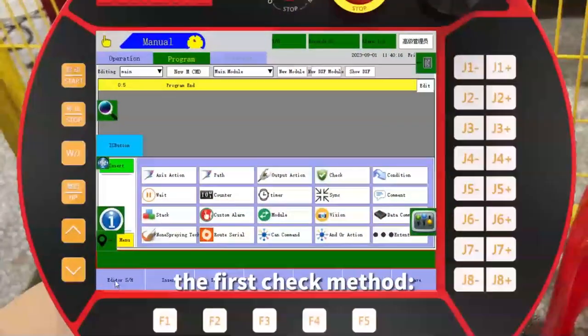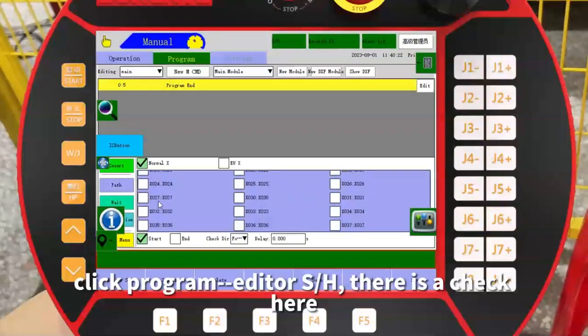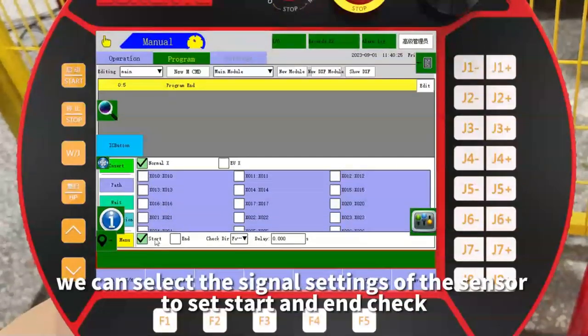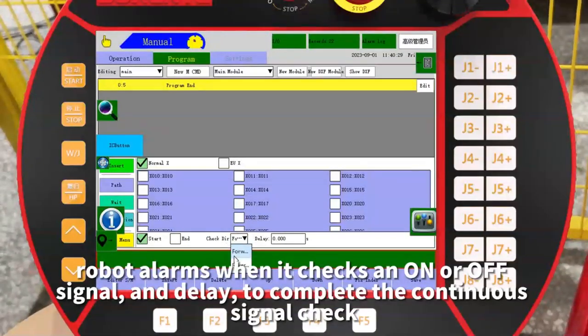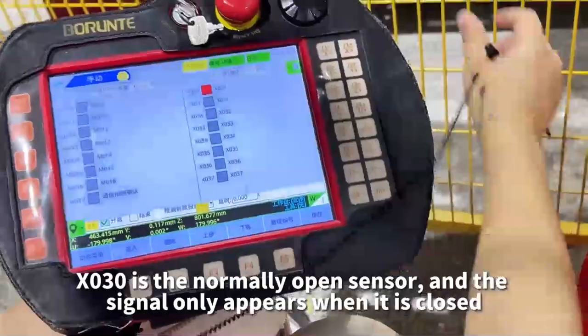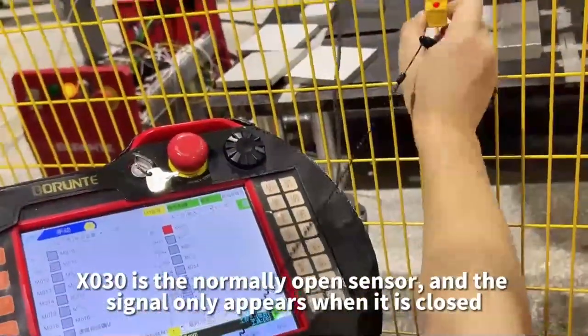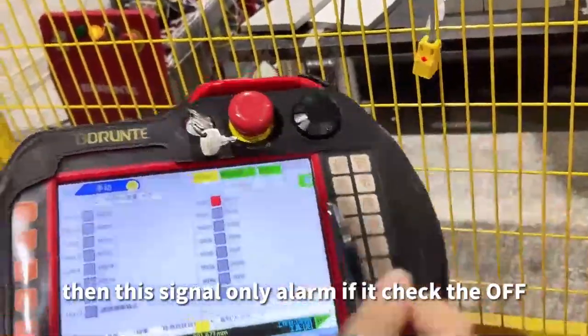The first check method. Click Program, Editor, there is a check here. We can select the signal settings of the sensor to set start, and then check. The robot alarms when it checks an ON or OFF signal, and delay, to complete the continuous signal check. For example, X030 is a normally open sensor, and the signal only appears when it is closed. Then this signal only alarms if it checks OFF.